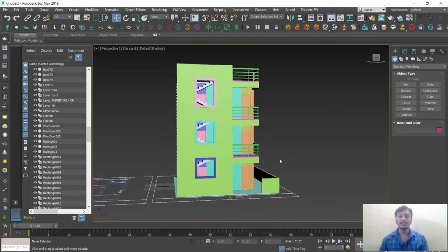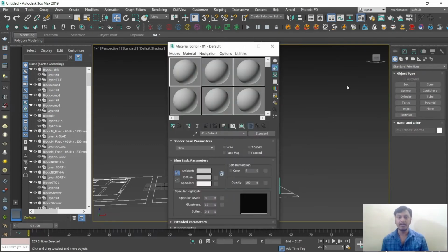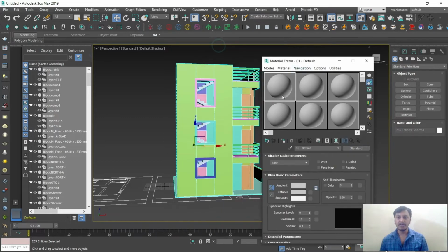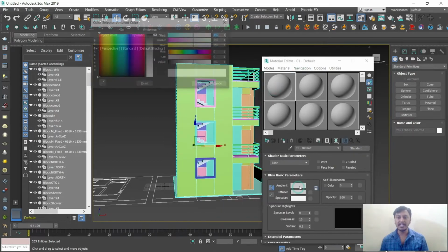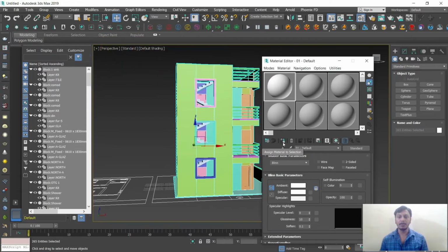So now I need to add a color actually. Yes. So we'll start with adding the colors. How to add a color? So first of all, add same color for all the places. Press Ctrl A, it will select all the shapes or complete model. Press M, M stands for material. So select your material. So select the material, change the ambient color. Ambient means your color. And the third one, so assign material to selection. Just click that. Now you can observe everything is in white.